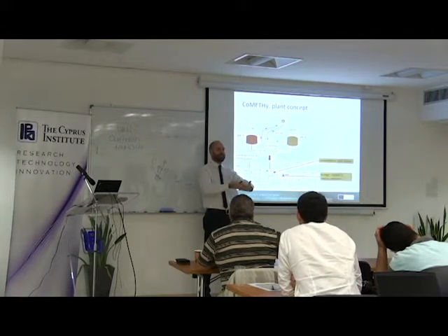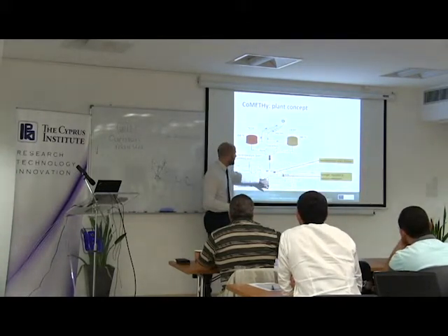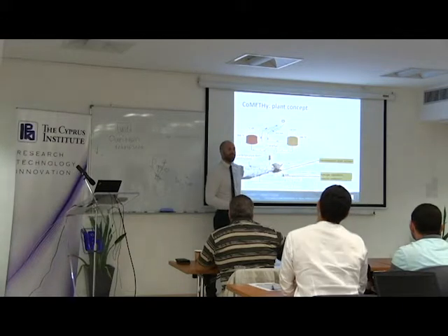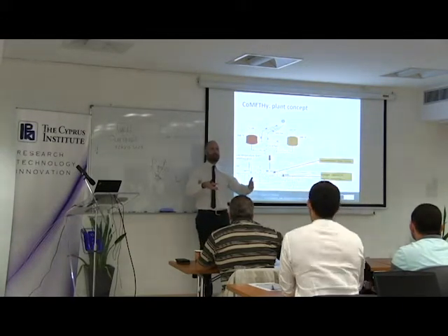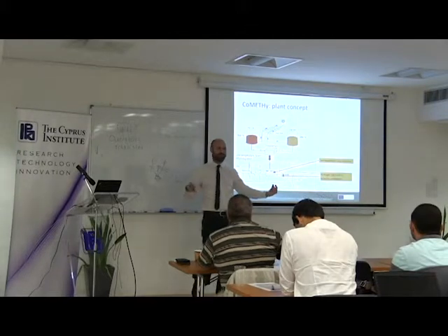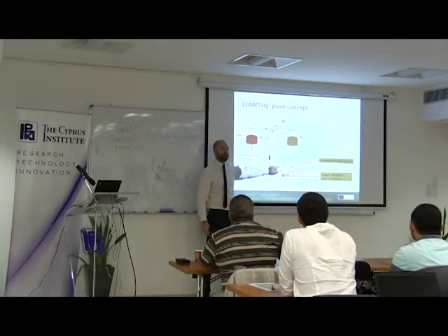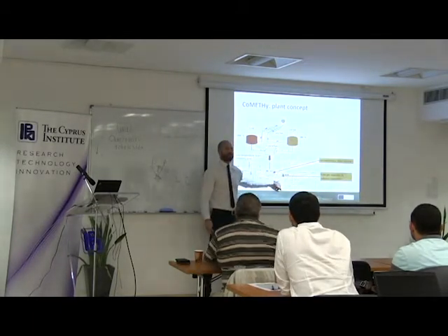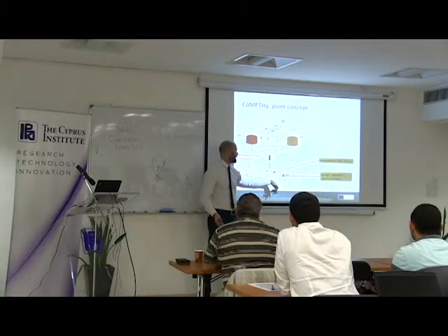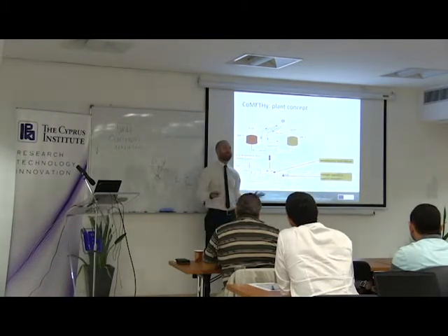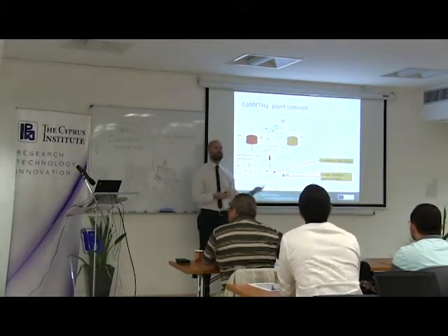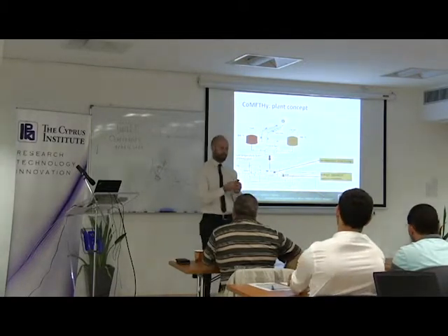In this case, the membrane is separated from the reactor in this schema. In reality, they are integrated, and I will show you how in the next slide. Another very good point is that you get pure hydrogen downstream of the membrane. Usually, after the reactor in an industrial plant, you need separation steps to recover pure hydrogen. In this case, you're already recovering a pure stream of hydrogen. Then you have some residual hydrogen in the effluent together with carbon dioxide. But in this case, carbon dioxide is highly concentrated, and highly concentrated means it's also much easier to capture compared to other conditions.